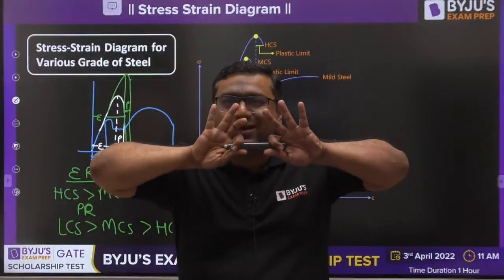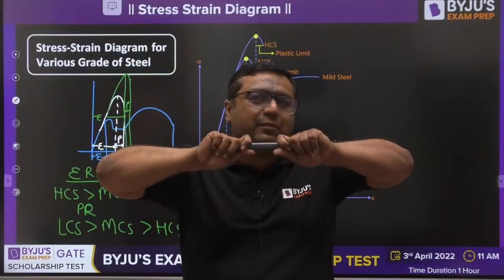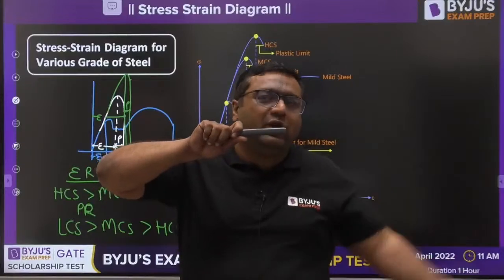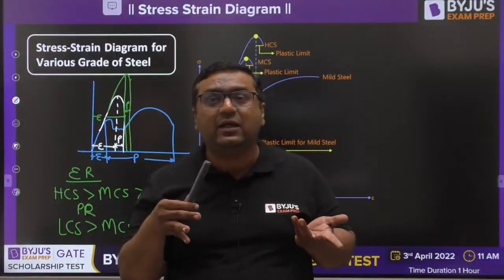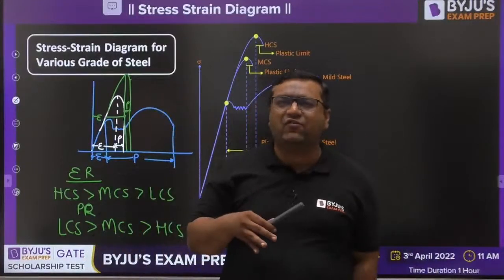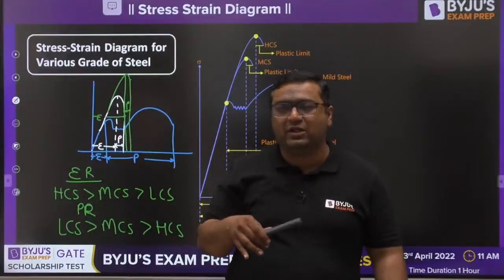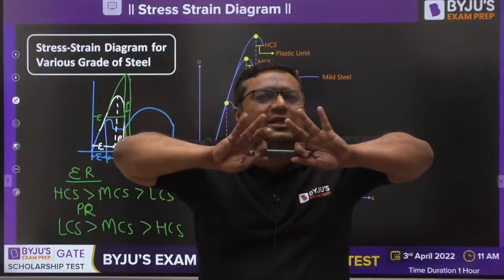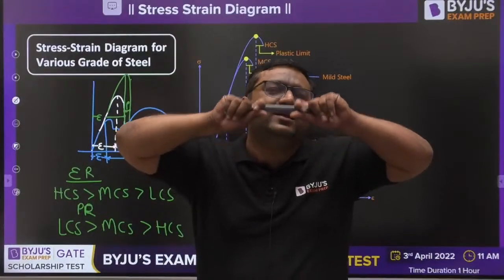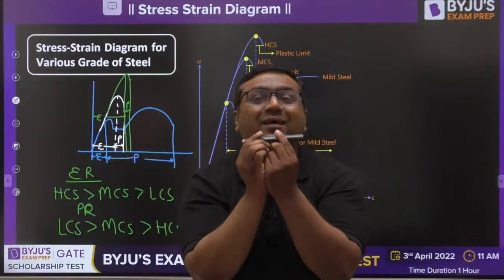Yes, for sure. But my dear, if it is totally elastic material, after removal of load it would be converted into the rod again because of elasticity. So we don't want elastic deformation, we want plastic deformation. If you apply force and after the elastic region there is a lot of plastic deformation, then after removal of load it will remain a wire.